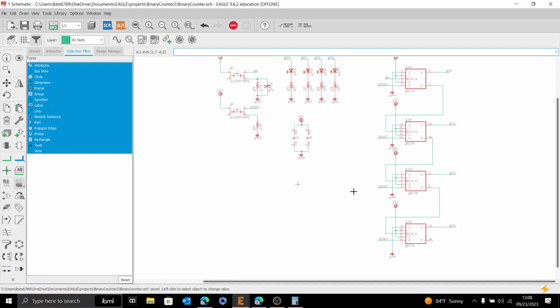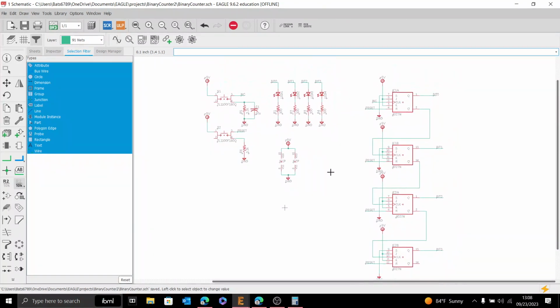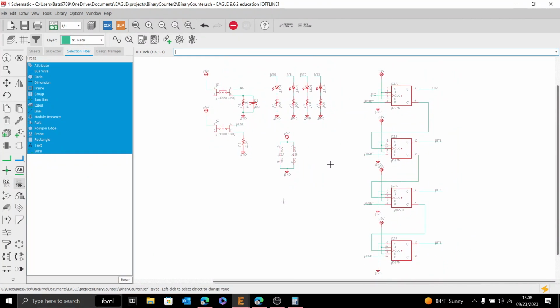So I was literally just about to talk about the bill of materials, and someone beat me to it. After you finish laying it out, ideally at this point, you'd take out a breadboard, lay out your components, and test it. That would be the smart thing to do. You could also go straight to manufacturing and order it like I did and find out it's wrong. Depends on how much disposable income you have. So let's assume you're going to actually test it and prototype it first. Eagle does have a way to generate a BOM.